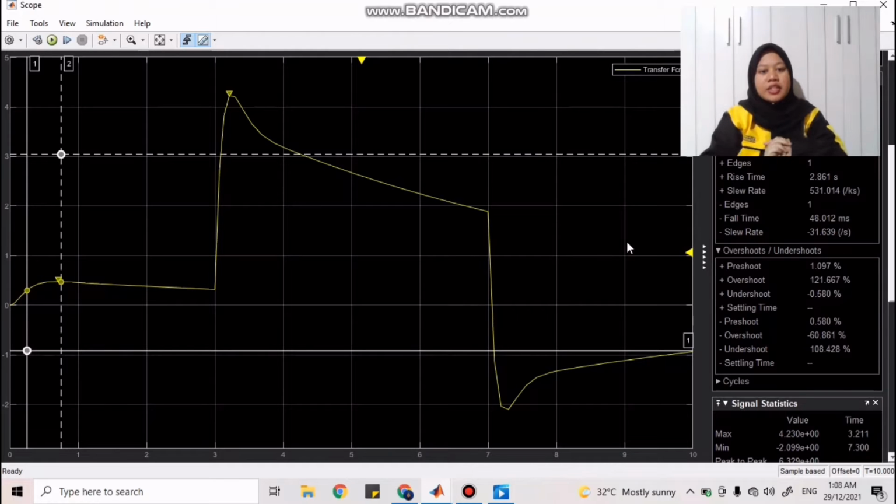The advantage of a feedback control system: using feedback in closed loop systems will improve control by automatically adjusting the controller output to reduce the error. This helps reduce the effects of dynamic disturbance. Feedback also adds stability to an unstable process, ensuring a repeatable and reliable control loop.